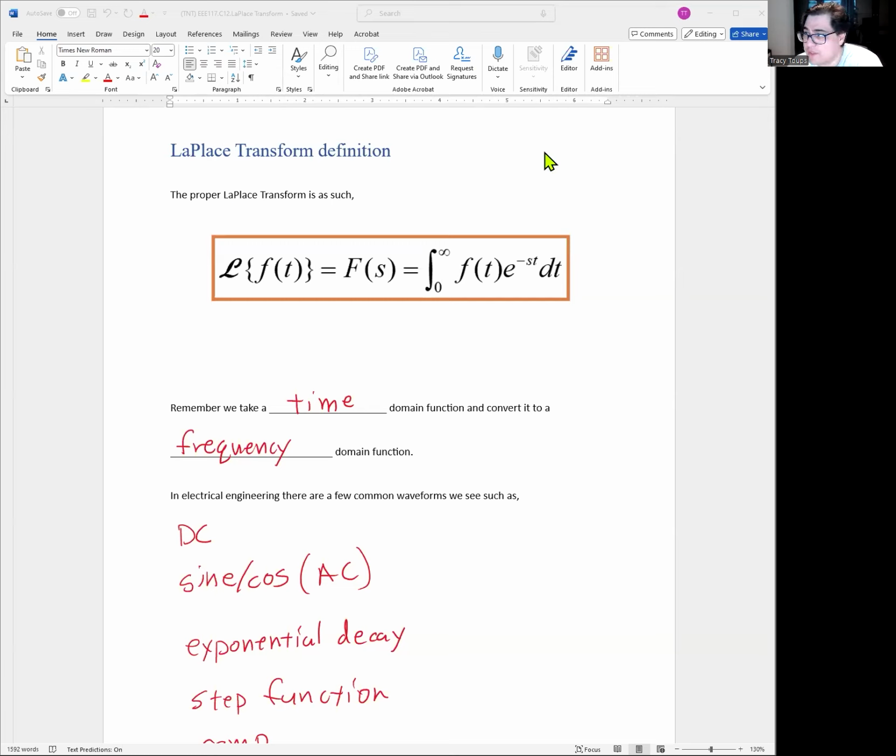So last time we talked about why we want to do Laplace transforms: basically going to a frequency domain versus doing everything in a time domain. Specifically, when we're using AC sinusoidal sources with inductors and capacitors nearby, the second order differential equation gets really, really hard. It's actually easier to switch to the frequency domain, do our analysis there, and switch back to the time domain. So the Laplace transform is helping us switch to the frequency domain.